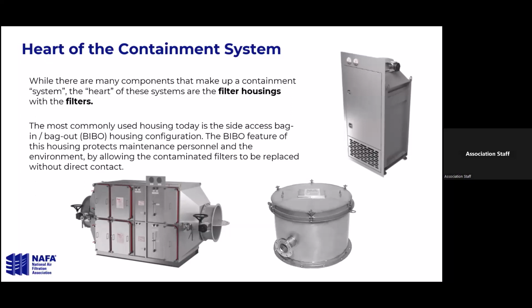The bag in, bag out feature is what helps protect the maintenance personnel. During that procedure, they're going to be protected from what's inside that housing while doing their filter change out. And this is where that NCT2 certification that was mentioned earlier comes into play, and knowing how to do that bag in, bag out change out safely.